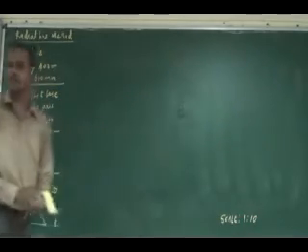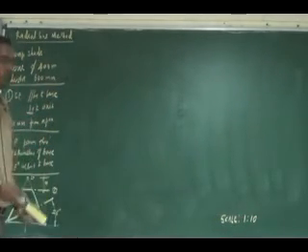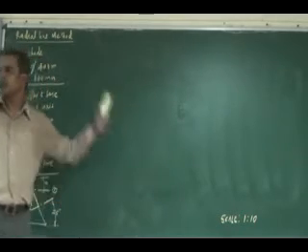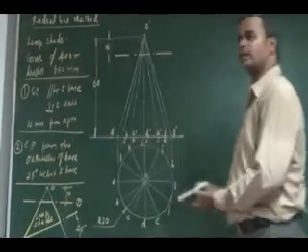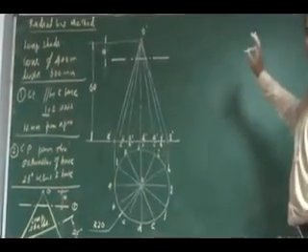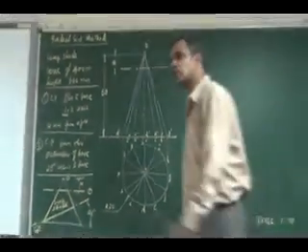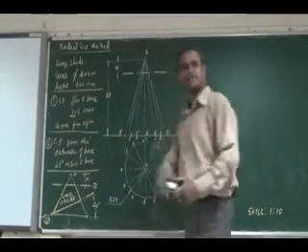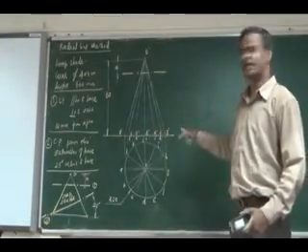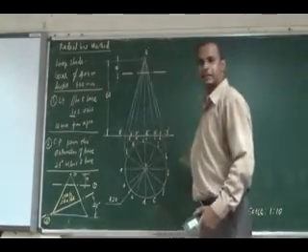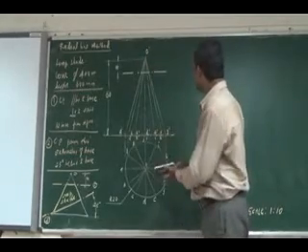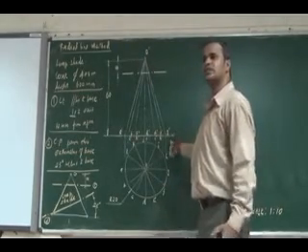Use the 1:10 scale. Then you draw the development. You draw the projections of the cone. Make it fast. You draw the projection of the cone. See here, as far as the development of a cone alone, you know, it's a segment of a circle of radius equal to the generator length. So the radius is equal to the generator length.